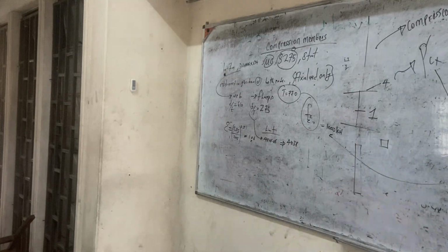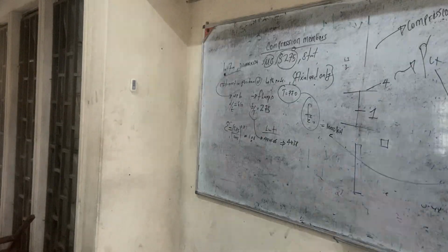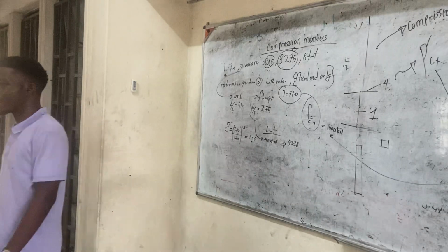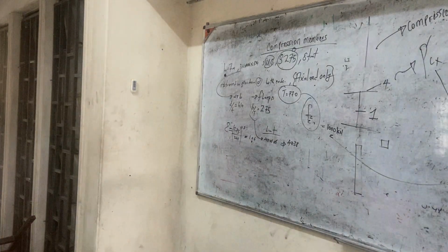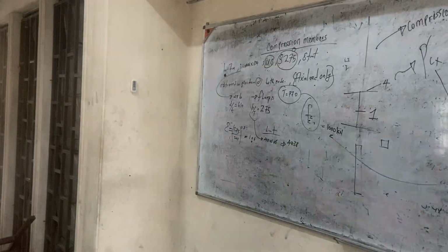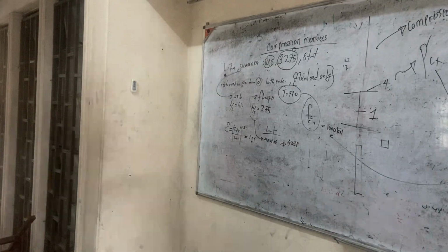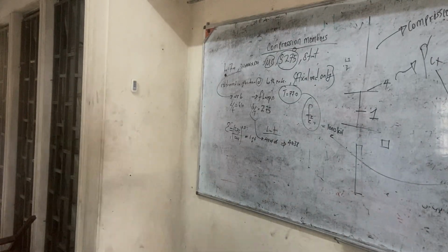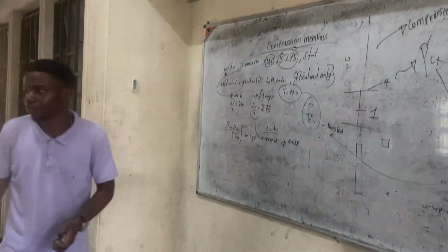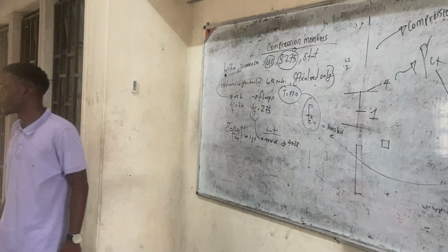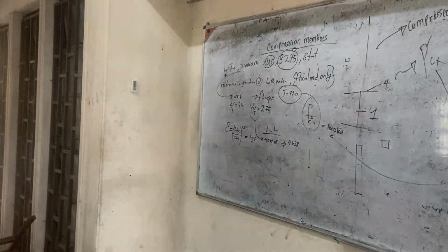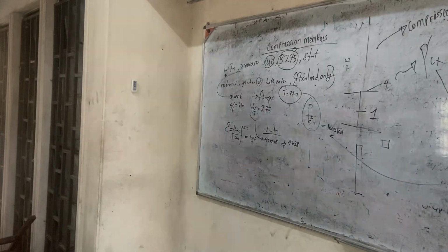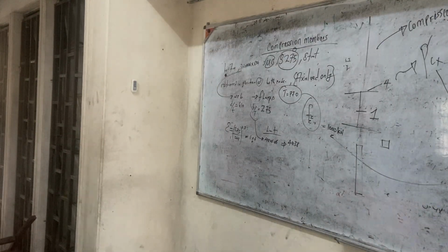For this question, we don't solve for the flange or the web, because it's already classified. The flange is classified. Exactly. But what if the flange was class 1, and we don't know what the web is eventually? So we need to assume FC. So I will just say that we are supposed to have FC. We classified the flange as semi-compact. Yes. But what if in another case, we're lucky here? What if we had class 1? Class 1.